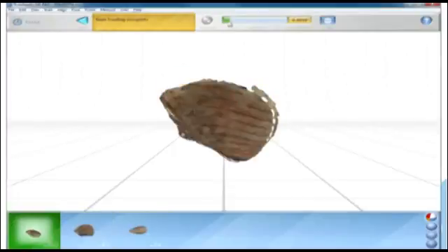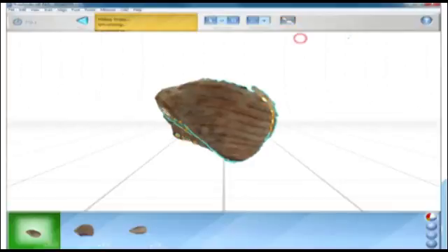You can then go through, if you wish, and fill in holes. You can automatically search for holes, and you can, if you wish, fill those holes. Now, we've adopted the policy that if they're just very small holes, we might automatically fill them, but certainly where there were holes of any size, we would try and do another scan to fill those holes.